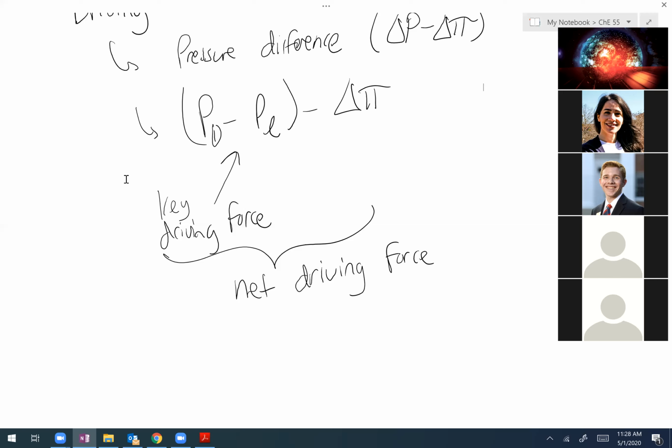It really depends. That's tricky, and I don't want to get too lost in the weeds here. Pressure is the easiest for a majority of separations, primarily because that's what's being used as a driving force. A lot of systems rely on the application of pressure to drive flux through a membrane. Anything outside of that, for example if it's concentration driven, is going to be a diffusion mechanism.